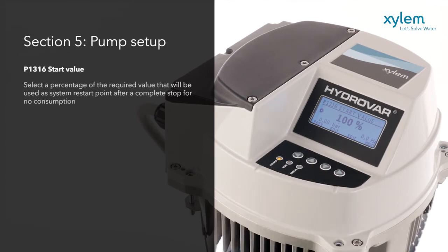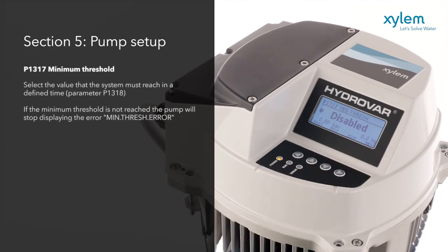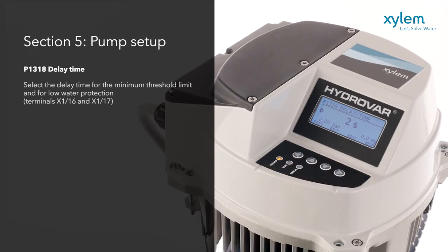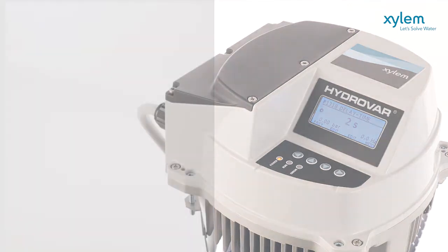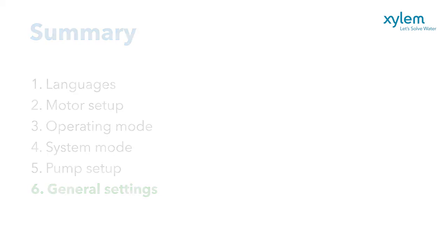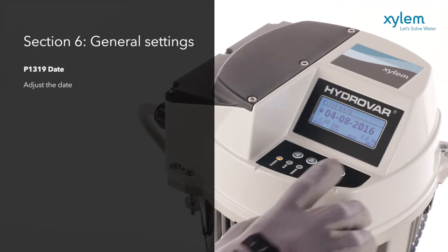Choose the starting point for when pressure drops and the minimum threshold for the pump to turn off when pressure or flow does not make duty within a set time. Similarly, delay times and water protection thresholds can be set. The date and time on the embedded time clock can then be set.